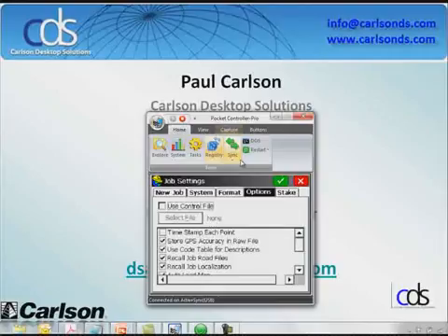Now, there's a lot of information in the GPS vectors. I am not a geodesist. I don't claim to be. I'm not an expert here to tell you what every line of this information is. But essentially, when I look at this inside the RW5 file, I'm seeing the base position and the deltas. Right above that, I'm seeing the date and the GPS clock time that point was started. Below that, you'll see the TM note. That is SurvCE's timestamp. That appears if you have turned the time stamping on back under the main settings.